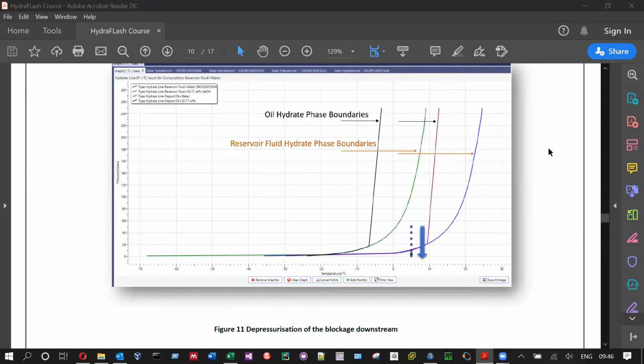Did I manage to pass my message here? Yeah, thank you. That's why I prefaced my comment with "in a known hydrate situation where you are remediating." In other words, you'll maybe go in subsea with a vehicle to inject methanol into an access point that doesn't normally have methanol delivered. But I'll take your point about the mixing and the phase boundary between the fluid interfaces.